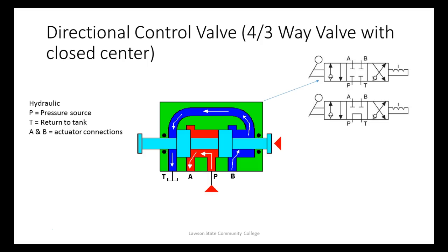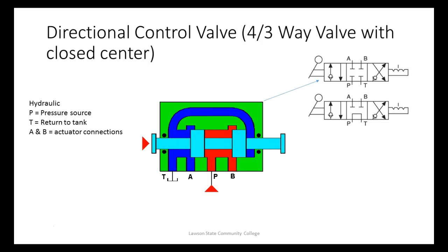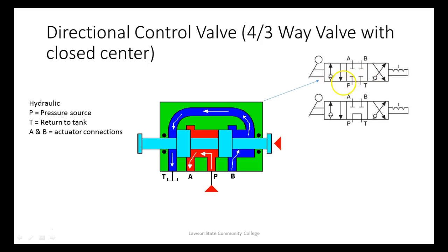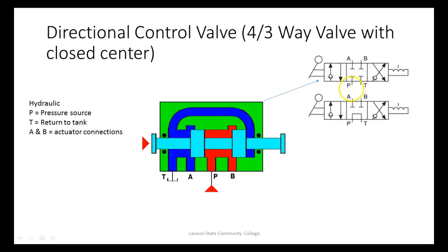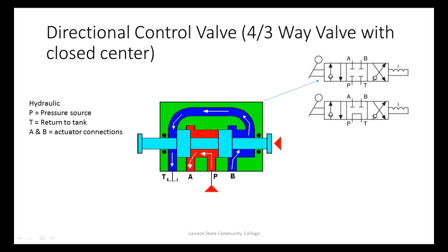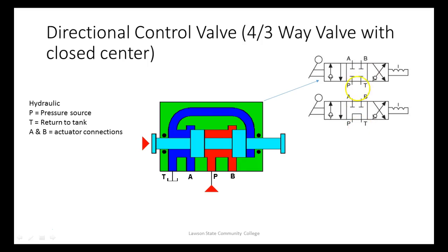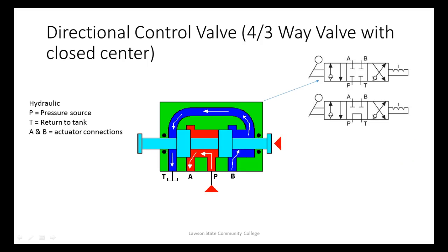So this would be a three. So look at this guy over here. So that would be a three-position valve with a manually operated, see that symbol? Manually operated. This has got a check valve in it, guys. I've never seen that before. That's pretty neat. This would be a three-position valve, right? How many ports? 4. So this would be a 4 three-way valve. And we'd say this would be what we call a closed center.